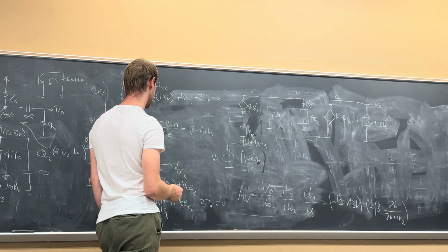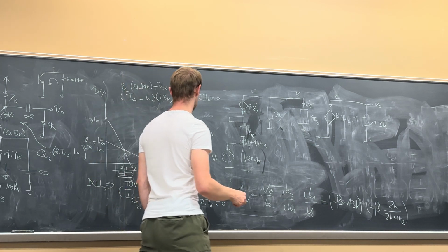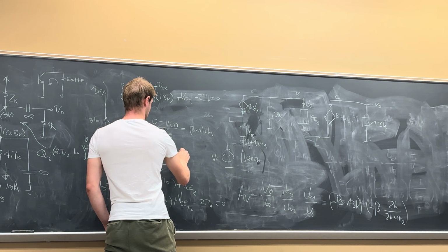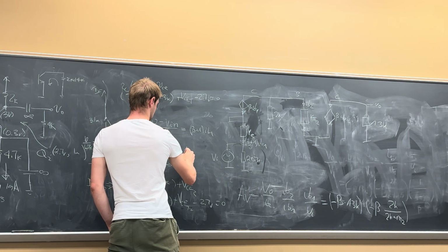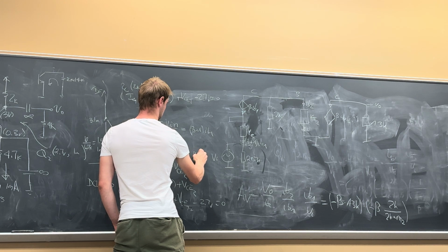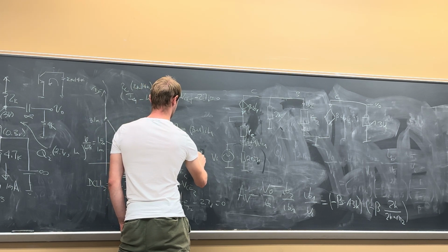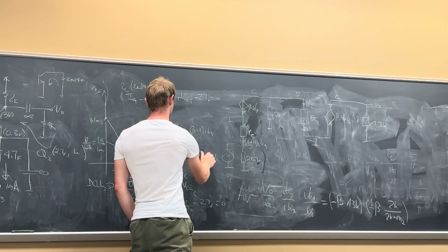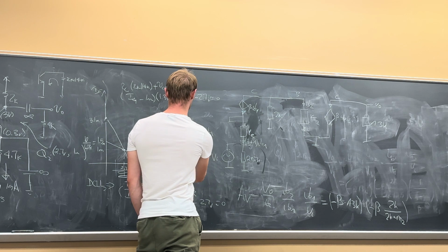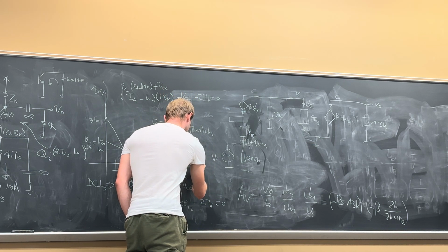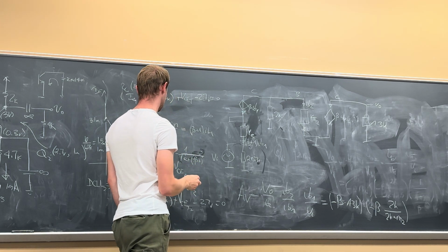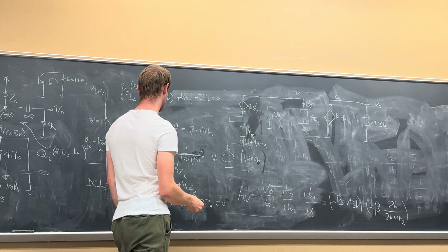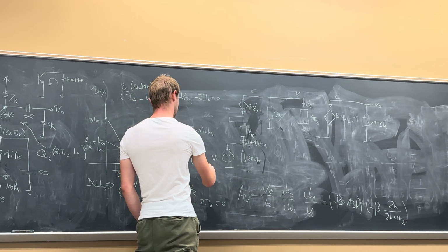IB1 over Vn. What do you get? Write it out over there underneath it. IB1 over Vn is equal to minus 1 over RE times beta plus 1 on the bottom. Yeah, put the parentheses there. No, RE times beta plus 1, I'm sorry, yeah. Which is equal to 1 over R pi. RE times beta plus 1 is R pi.